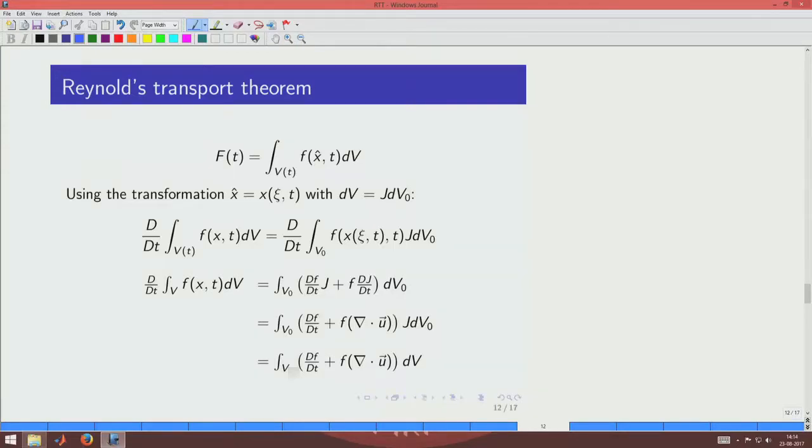If you take any quantity that is expressed as a density, then if you integrate it over the control volume, you get the quantity out. Take the example of the small f. If the small f happens to be rho, then the capital F would be the mass. And in the case of small f being the concentration, the capital F would be the amount of solute for that particular quantity. Like this you can think of any quantity that is specified as small f, and respectively you have capital F also defined.